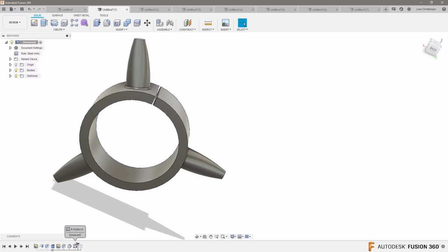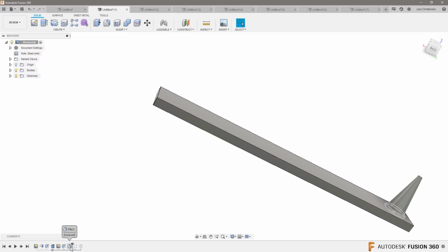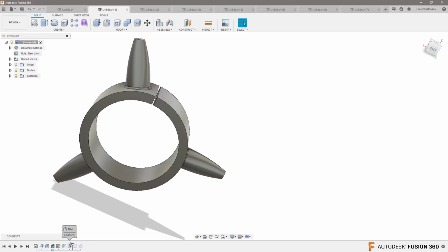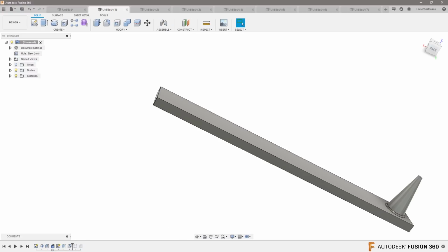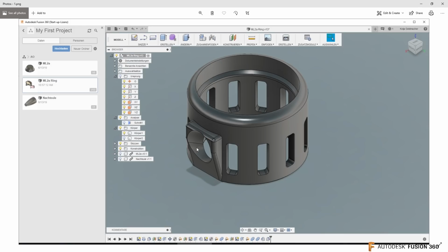So you can always go back in the timeline, drag that handle back, and add your fillet to it. That is really what you want to do with this part. Just take this timeline down here, drag it all the way back to right there, add your fillets to it, and then drag it forward again. You might have to go in and edit just like I did, and include them inside of that operation right there. Hope that was useful.